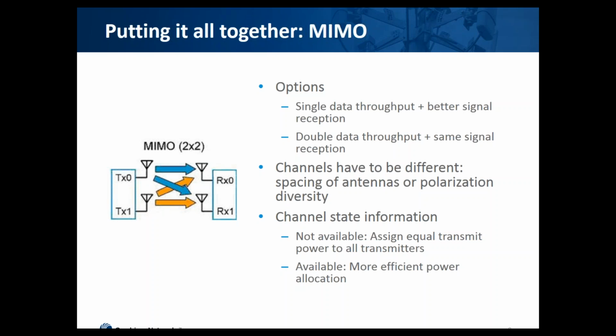Imagine that in the first transmission you send waveform S0 from one antenna and S1 from the other. But in the second transmission you now send waveforms S2 and S3. You now have sent 4 waveforms in 2 transmissions, so you have doubled your throughput. This means that the video you are downloading will take half the time, or that one access point can serve 2 devices at the same time without slowing down anybody.